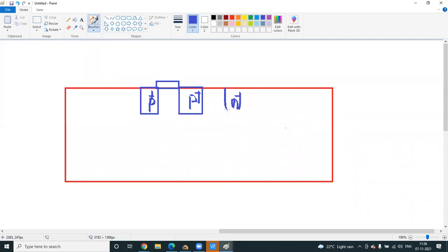You are able to see this is your NMOS and PMOS. PMOS means P channel. The gate is like a controller, like a water tap. If you see your water tap, the tap is controlling. So the gate is controlling your channel. Suppose you apply a positive voltage, the negative will be created here. If you apply a negative voltage, the positive will be created. So the channel will be created.